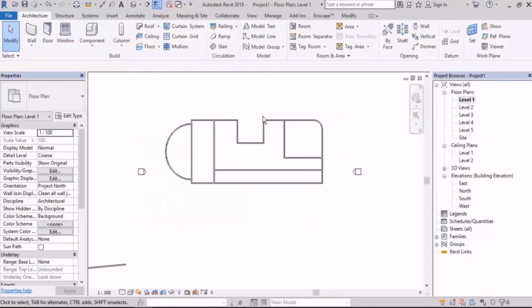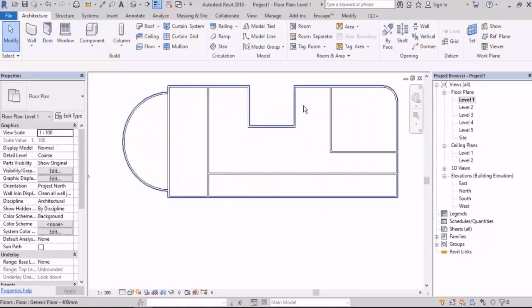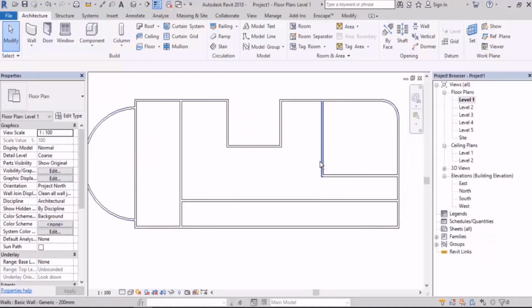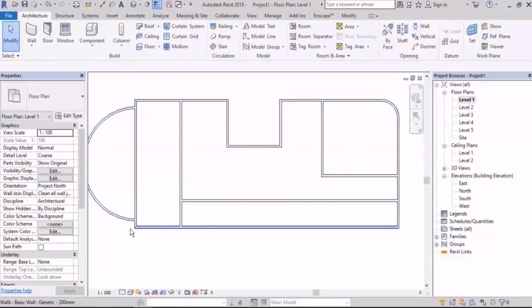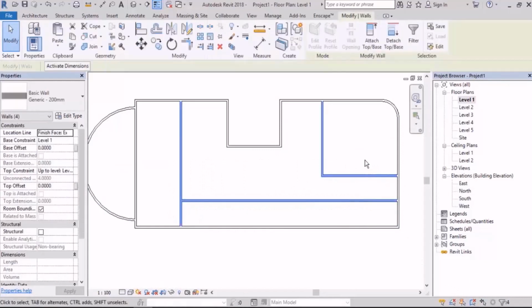You might also think, why is there an on and off key for this? It's so useful, why would we want to turn it off? But I tell you, that's wrong. Many times it's an encumbrance. But when? Imagine that now I want to open a box to select all these walls. So if I click here to open a box, instead of that, it selects the floor. Well, I don't want it. I want to open a box. I want to select my walls. In these times, either I have to wireframe my view or turn this off. You see, because if I click it instead of opening a box, it selects it.